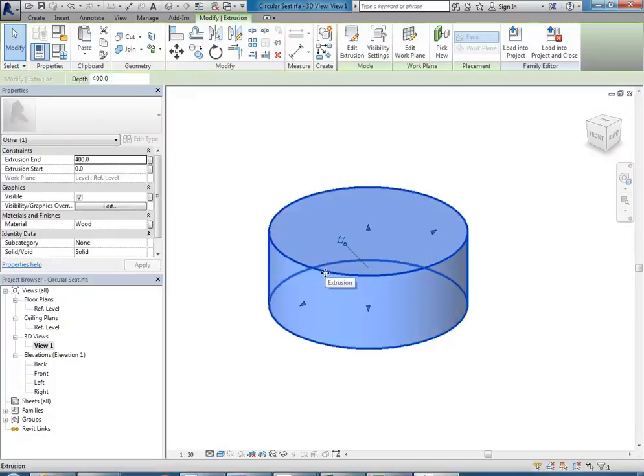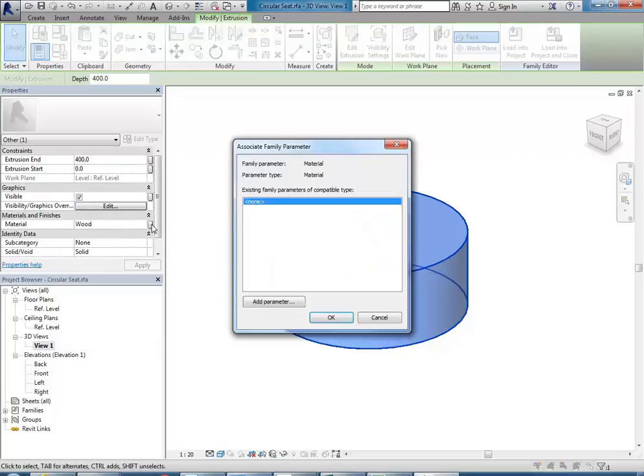And this, like I was saying, is a brief intro to parameters. And you'll find that over here, the button at the end that you may have clicked on by mistake and wondered what it was for, is to assign a parameter. It's not to assign a material. So here's material, there's the material I've assigned, and then at the end is that grey button which associates a parameter.